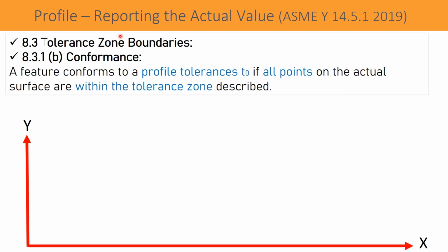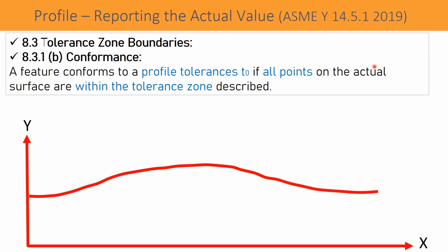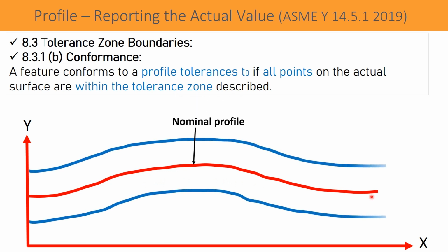When the report is given graphically, showing the conformance is very easy. It represents exactly how the profile is within the tolerance or not. For example, this is a true profile, the nominal profile, and there is the bilateral tolerance zone, indicated here as T0.